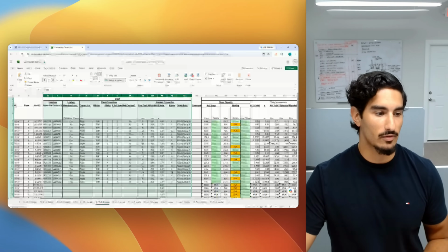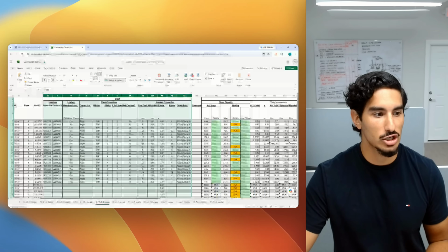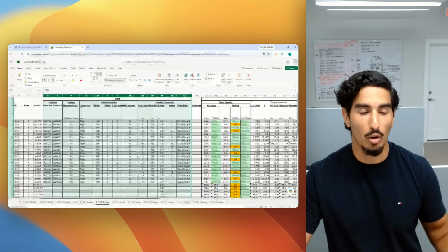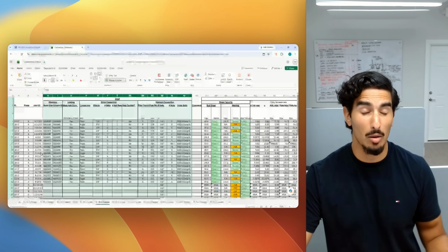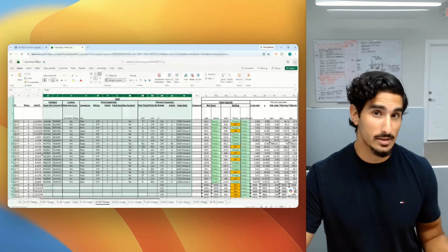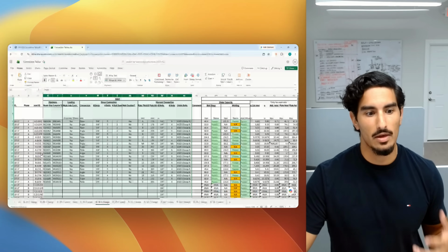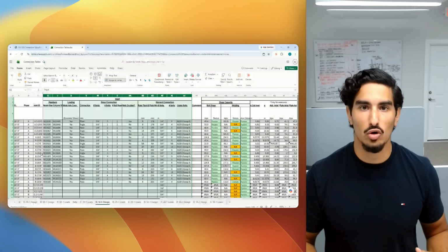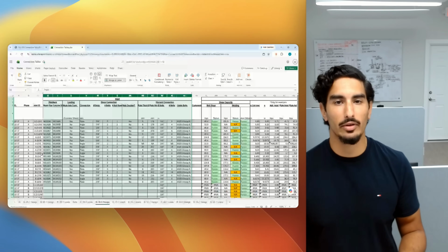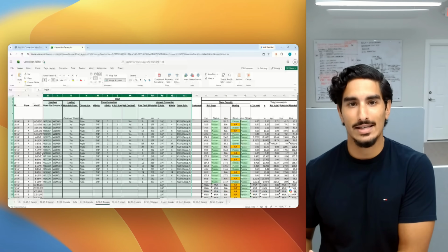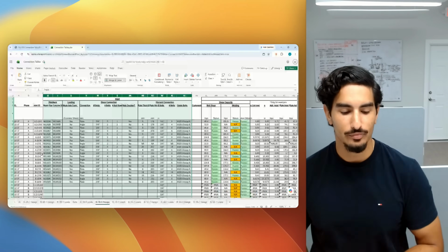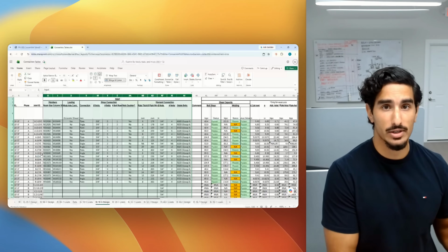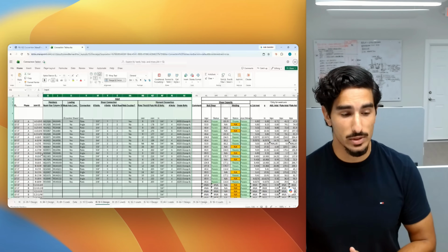So we needed to look at the different types of members that were getting framed to the connection, whether it's a weak axis or strong axis connection, different connection types, the bolts being used, whether there were doubler plates being used on the columns in the instance of a weak connection, and then going through both the shear and the moment connection. These were all different variables that we were trying to identify and then populate a spreadsheet with to figure out what the utilization ratio was of that connection. And then once we understood that, we make the decision whether we had to reinforce the connection or we were happy with the state that it was in.